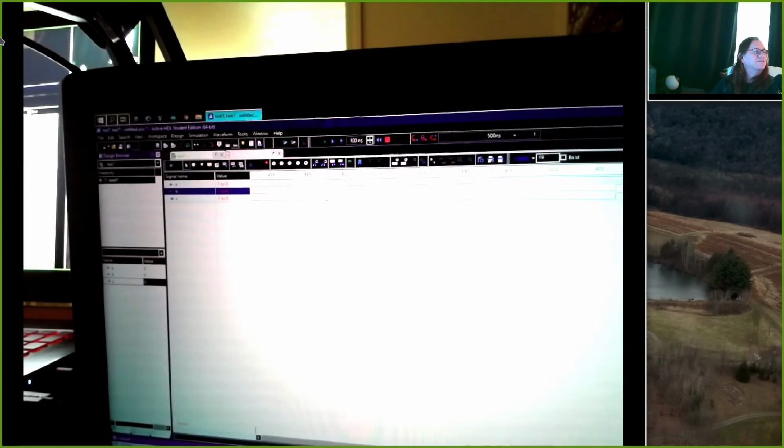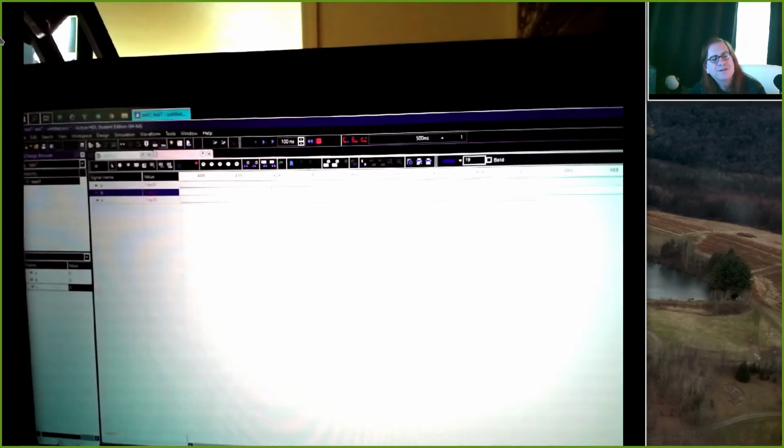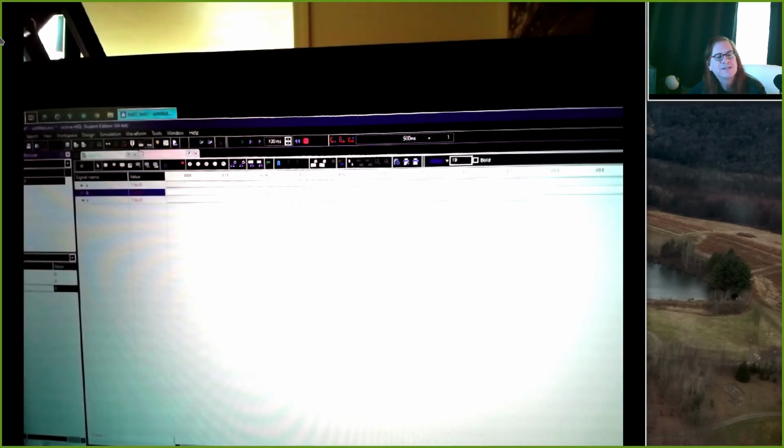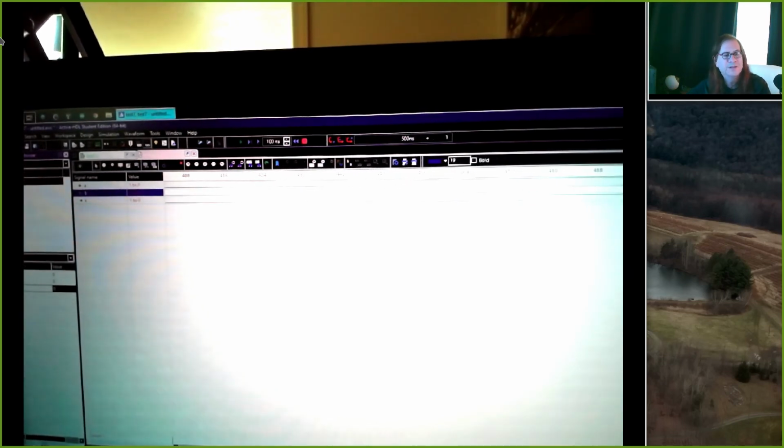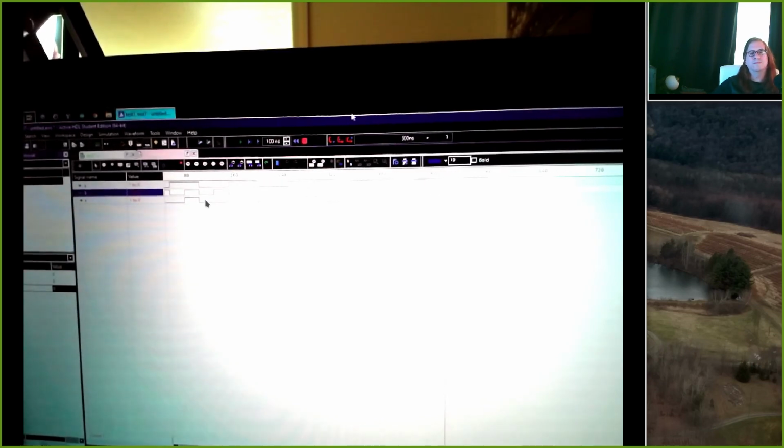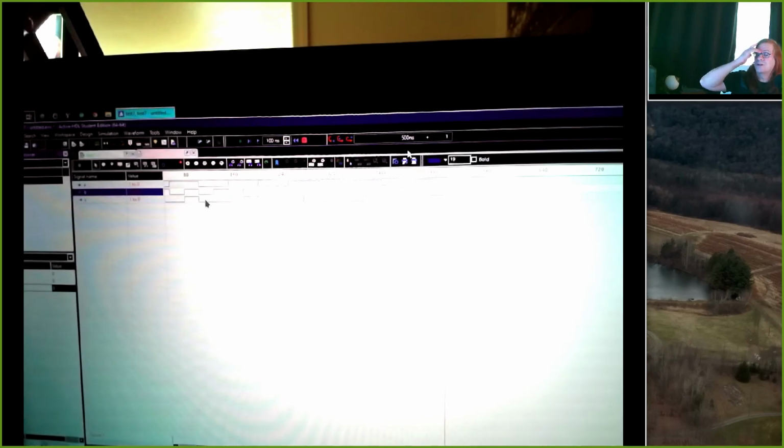But the effect is I've got 3 timing signals here, and the first one is modulating up and down fairly slowly. The second one is modulating twice as fast, and the bottom one is showing me an AND operation. So here we can see it a little better, right? So this first input is A, this second input is B, and my output X is 1 exactly when both of my inputs are 1, and it's 0 any other time. And so that's a simulation of our Verilog module.